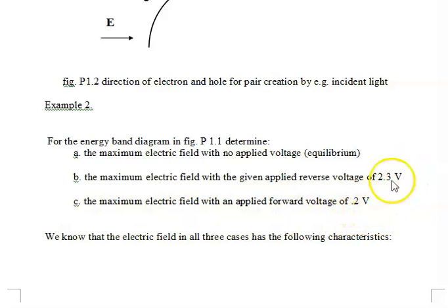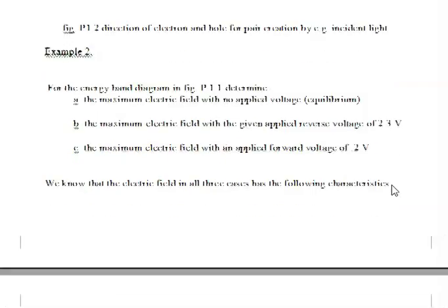Now you notice the differences in the magnitude. Forward bias is very small. There's only one barrier, and it doesn't take much to overcome that barrier. So 0.2 would be typical, 0.3 would be typical, whereas reverse bias, we can put basically as much as I want. Unfortunately, the current does not decrease as I apply larger and larger reverse biases, because the barrier is approximately constant, independent of reverse bias. So that's a problem with Schottky barriers.